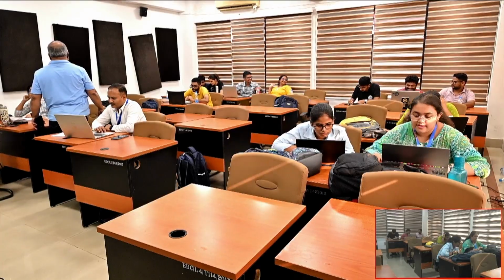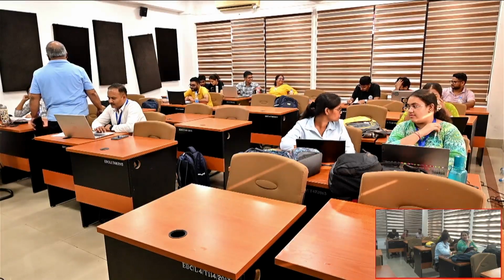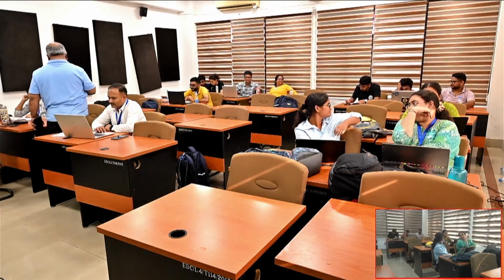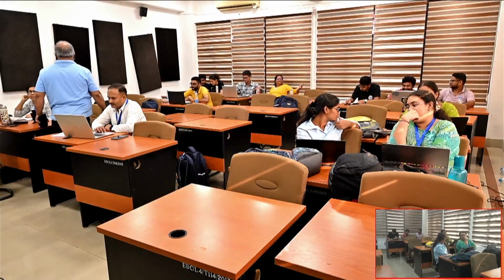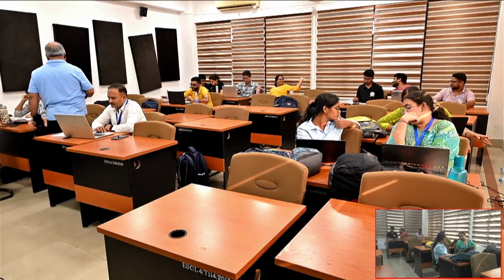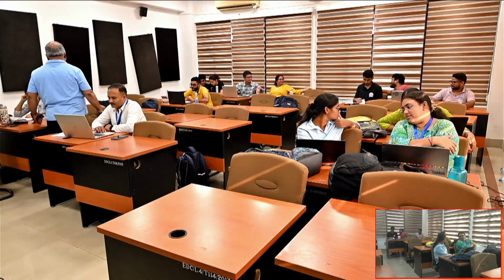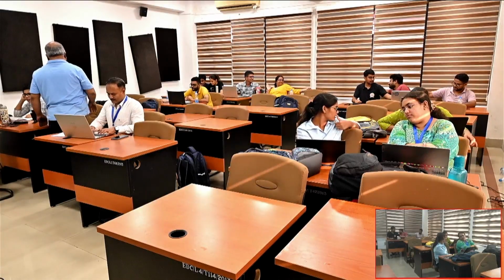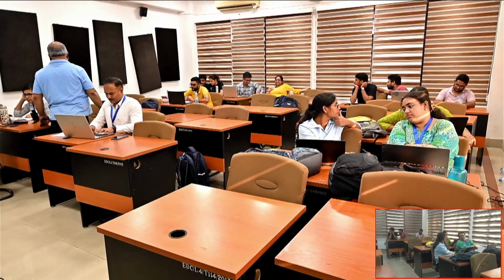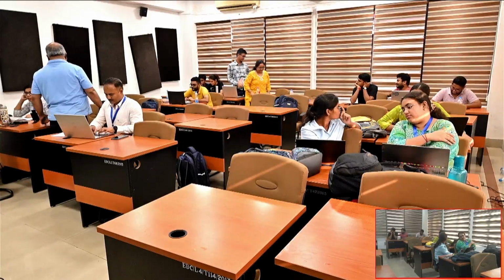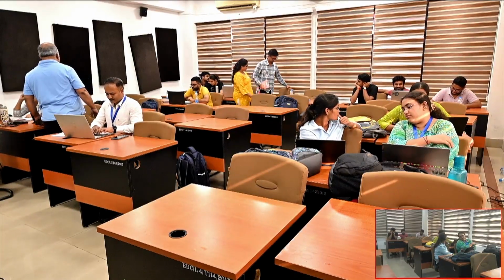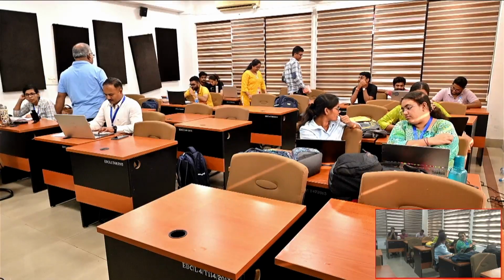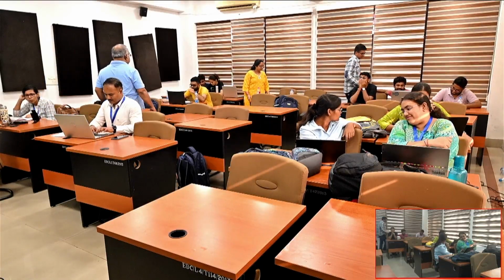Yes, so the distance value for the epicentral distance will not be that 52 kilometers. The epicentral distance for these stations is around 25-26 kilometers. So maybe you can put it manually now. We'll be seeing that afterwards. The TS minus TP calculation is not correct.